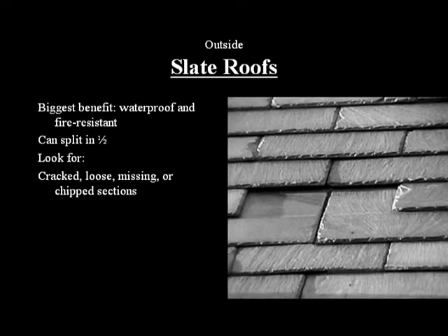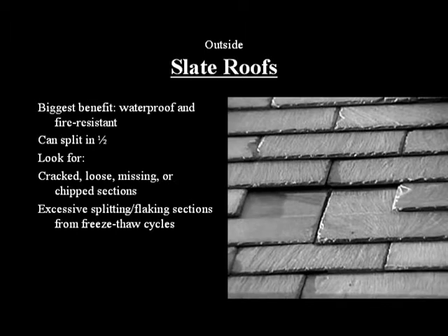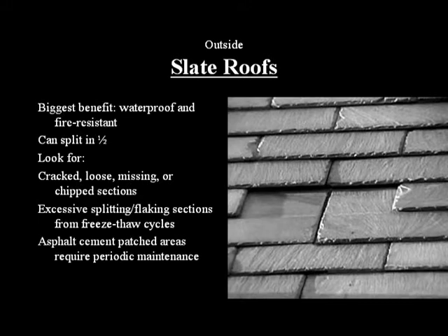If you see a section that has excessive splitting or flaking, this is probably caused by the repeated freeze and thaw cycles of water. And finally, areas patched with asphalt cement require periodic maintenance.